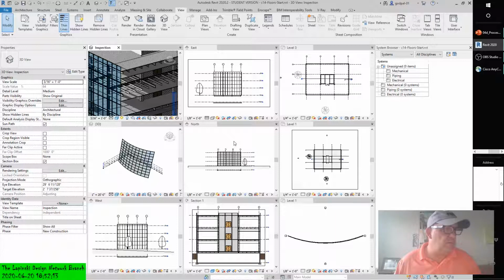You can create a structural floor by selecting the floor element and clicking the instance property called structural. Because structural is an instance property, any floor type can become a structural floor. After you select the structural parameter checkbox for a floor, you can edit its type properties to add a structural decking layer. Let's create a new structural floor so you can explore how this is done.